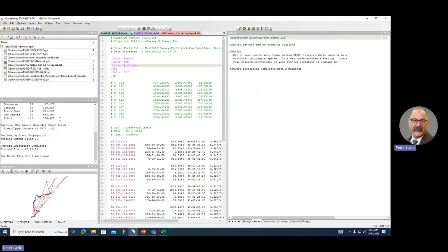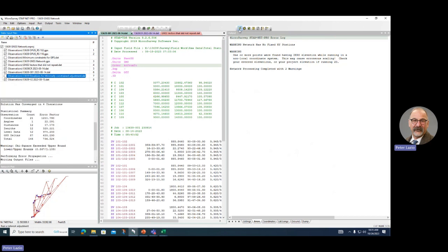Yeah. Wow, sheesh. Because it's holding those zeros. It's trying to hold the constraint elevations at 0 for every single instance of that point. Yeah, so you can see that being an issue. When you see that happen, yeah, don't panic. You just click up. When it gets that bad, it's usually something you did. It even gives you a warning saying that. I guess that's actually like a good safety net for making sure that if you use 0, you don't have them click on with like a slightly off elevation.